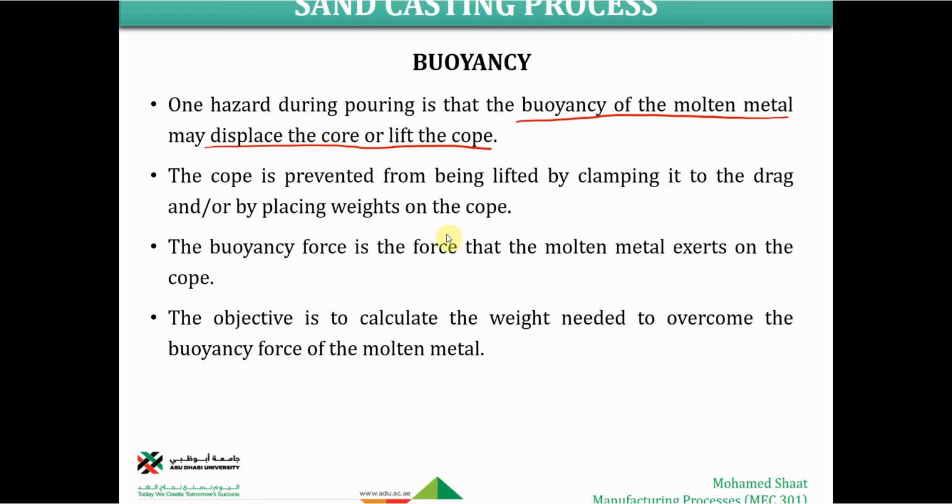In case the core is located horizontally in the sand mold, the buoyancy force will be a big deal, and it will start to push the core. In addition, it would lift the cube off the drag and will result in some displacement of the cube with respect to the drag, and this definitely will result in some defects in the product.